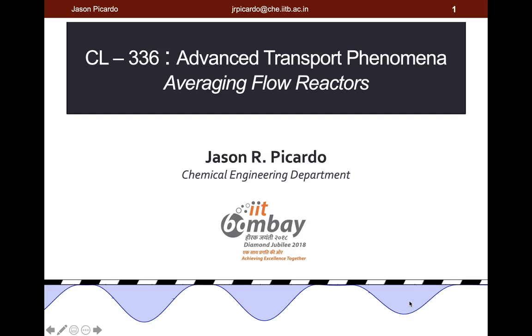we applied it and illustrated the method in the context of the problem of laminar dispersion or Taylor-Aris dispersion in laminar flow tubular pipes. And what we saw there was how, in the limit of rapid radial diffusion relative to slower axial convection, we can use the so-called method of averaging to derive a simplified model that made immediately obvious how differential transport due to axial convection appears effectively like a diffusive dispersion in the axial direction.